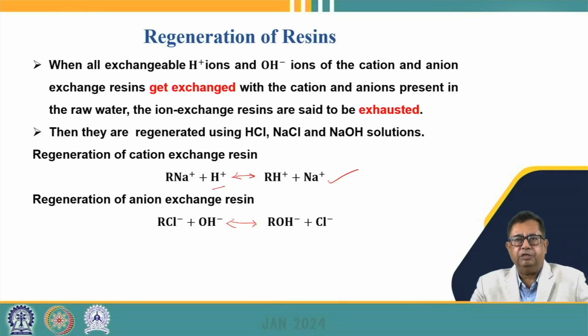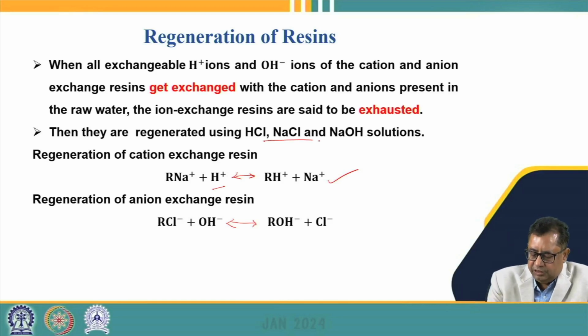It also depends upon the type of the resin that we are talking about. If it is a very strong resin, then we may increase the concentration of HCl, NaCl or NaOH. And if we have weak acid resins or weak base resins, we can reduce the concentration of our regenerant. So they are also known as the regenerant.